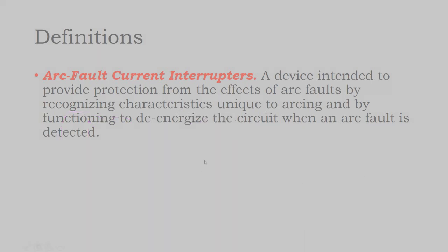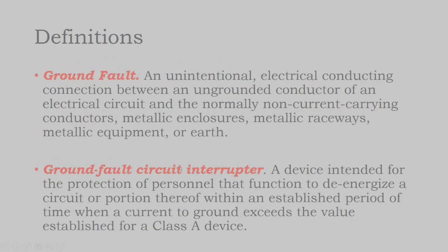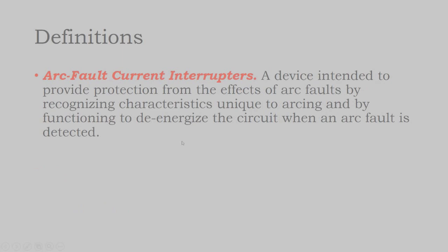And so National Electric Code over time has, it used to be that it just required ground fault protection and ground fault circuit interrupters. Nowadays, the inverters have arc fault detection in them as well.